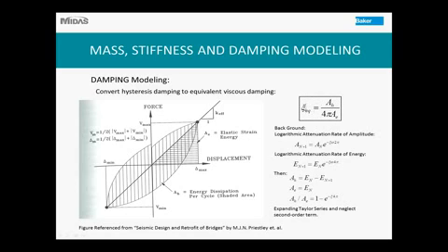realistically, for the case when you have Ah equal to Ae, let's say the energy dissipated per cycle is equal to the strain energy at the start of the cycle, theoretically you should not get any vibration anymore, because that's the case we call critical damping. So there will be no vibrations. So theoretically, the equivalent damping ratio for that case should be equal to 1. If your Ah equals Ae, you should get 1. But in this case here, what you get is 1 over 4 pi, which is about 7%. So this equation is a conservative approximation of your hysteresis damping.